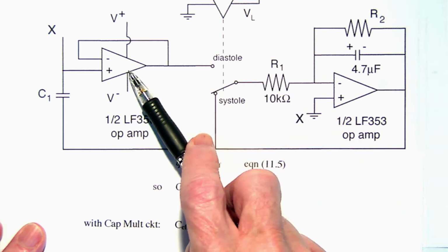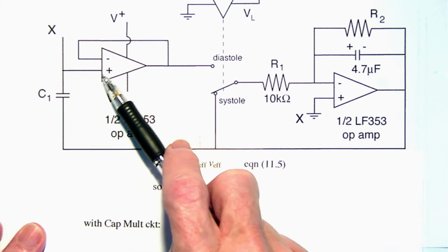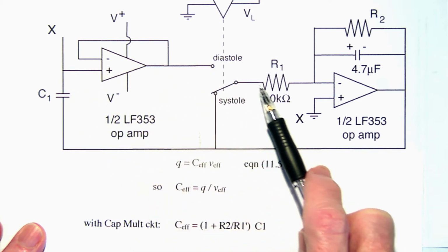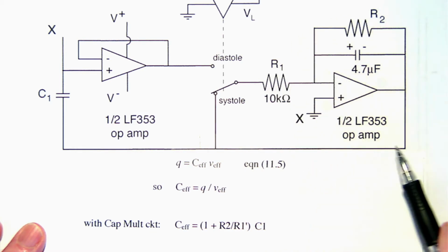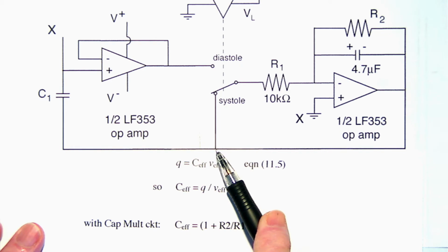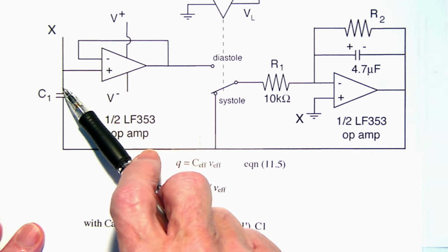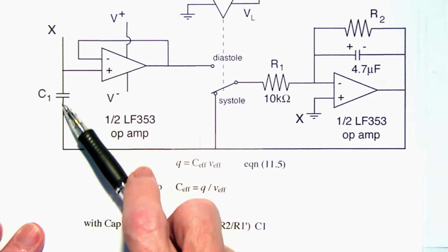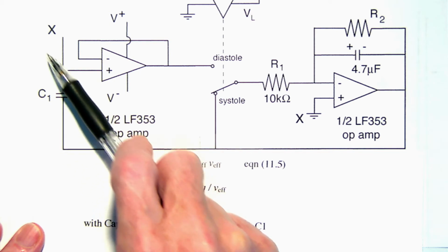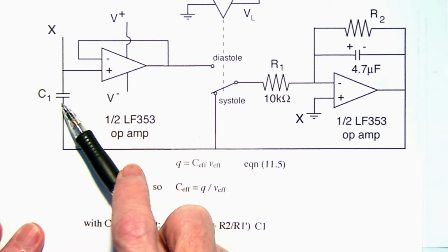The reason we use a voltage follower is to avoid taking any charge off the top of that capacitor in measuring its voltage. What that inverting amplifier does is it takes this lower line now to a voltage below ground. It is not ground anymore. And that drops down the voltage at the lower plate, thereby dropping down the voltage at the upper plate of the capacitor. And when the voltage drops down, that effective new voltage that the rest of the circuit sees at this point means that the rest of the circuit thinks that this capacitor has a much larger effective capacitance.